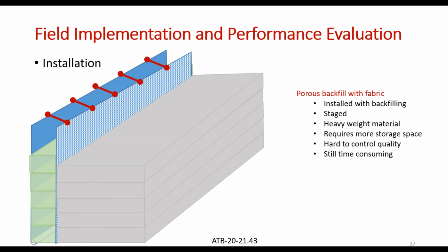the porous backfill directly into that. So the way they did it is they use a backfill bucket. I'll show you a picture about that. They shake the porous backfill very gently into that narrow space from the bucket of that backfill. So you need an operator, and you also need a coordinator to guide that person to gently shake that down. But it's a tedious process as well. It's also time consuming.